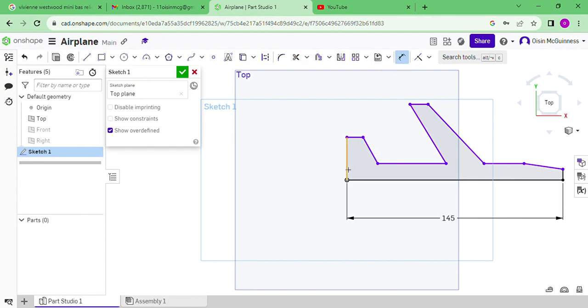So we're going to put in, instead of just clicking and dragging out, we're going to click the 2 points that make up this back line. So click this point and this point, let go and drag over. We're going to type in 30. For this line here, instead of just clicking and dragging out, we're going to click, drag out now and type in 10. So this is just a better practice way of doing dimensioning. Give that an enter.